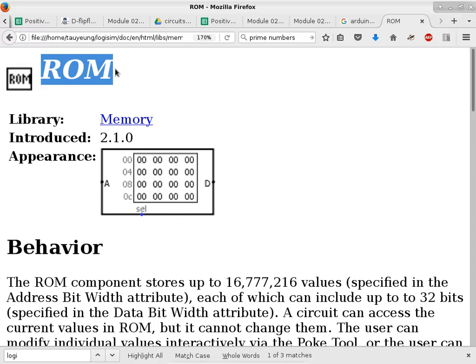So you can kind of imagine that is kind of inconvenient, because what if the first version of your firmware is buggy and you just fix something, right? So you have to ship out the corrected version to your customers, and that becomes a problem if you have to wait for the manufacturer to manufacture the next batch to you, and then you in return ship it out to your customers. So that's why the second generation are called PROMs.